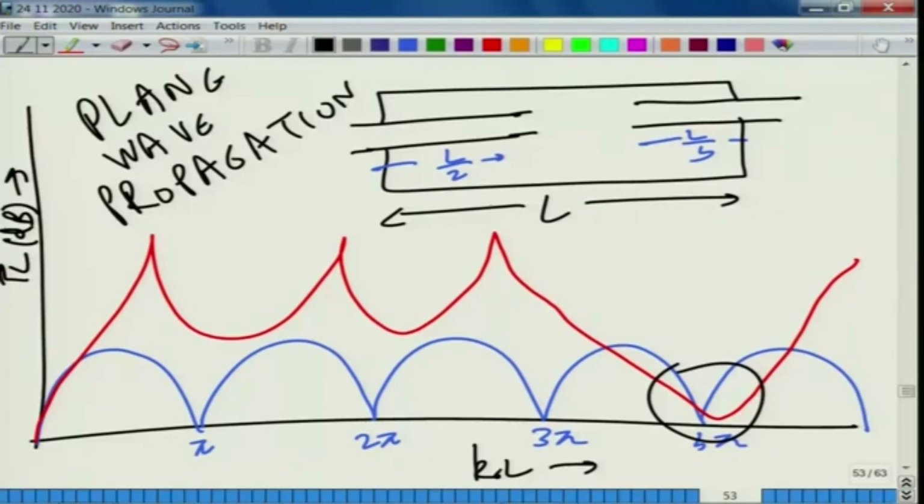That is important, assuming of course that the waves are planar, and these are all quarter wave resonators QW1, QW2. By this simple trick, we can possibly extend the broadband transmission loss range a lot. We can definitely improve the transmission loss performance.